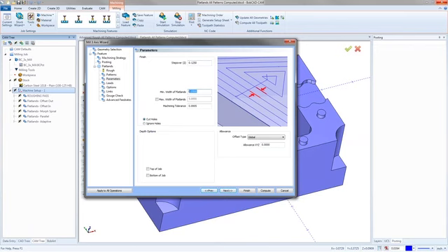Flatlands, so you have 2 options for your size of the flatland. Right here, we can see the minimum width of flatland. The smallest flat area that BobCAD will recognize and waste its time cutting is 50 thousandths. If you have a small ledge on the part that's smaller than 50 thousandths, BobCAD's going to ignore it. Now, if you have a large flat area, and in this case I'm using a 1/4 inch flat end mill, the best idea would be to go in there with a much bigger tool and clear that out a lot faster.